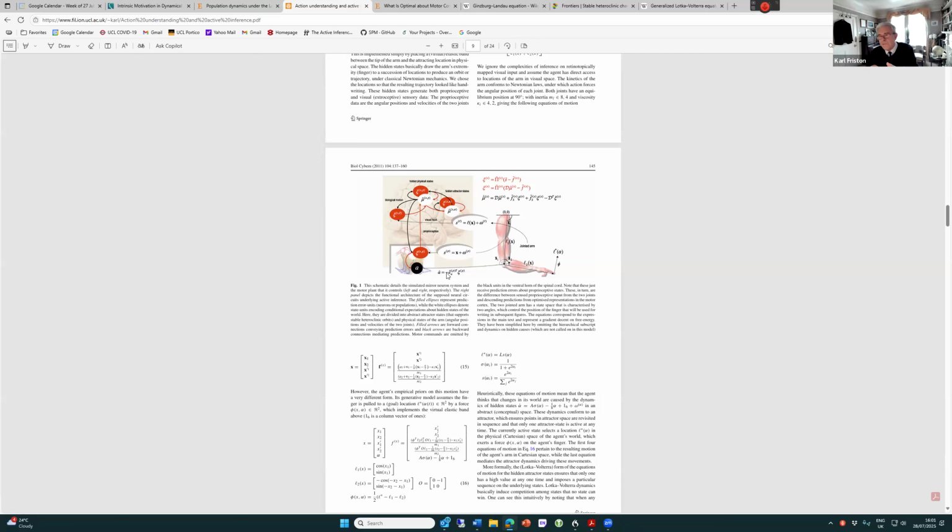But the closed loop is really simple, and all it means is that I've got this top-down prediction, which is how much stretch this particular muscle or what angle this particular joint should be at. And I get a report that this is the actual angle. And I know that if the angle is too big, then I'm going to reverse my motor and reduce it.